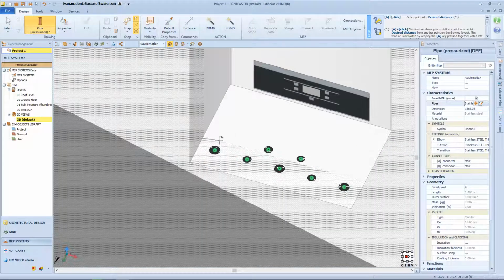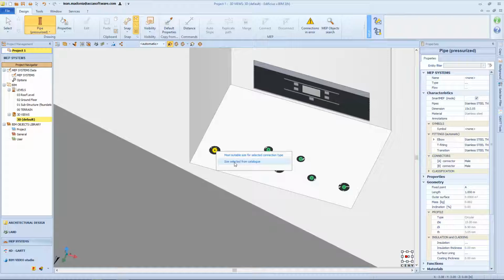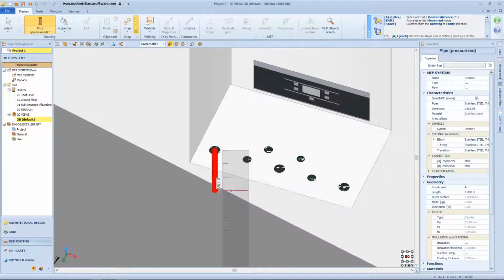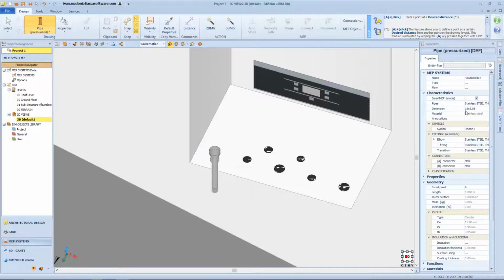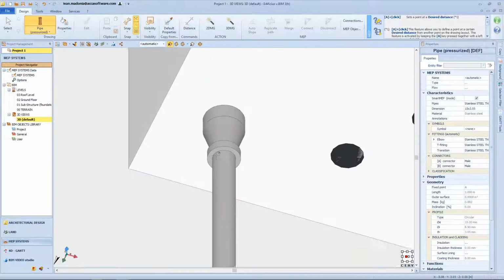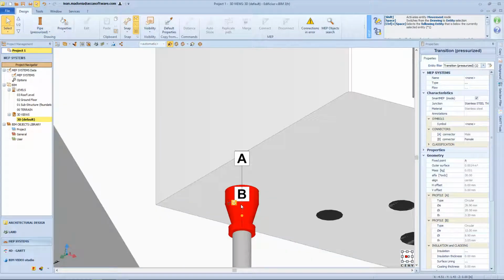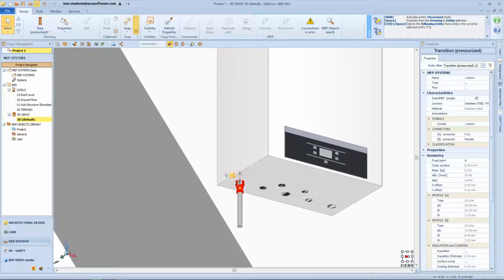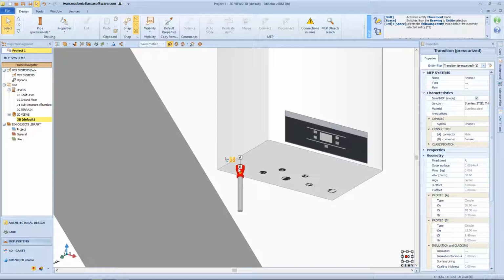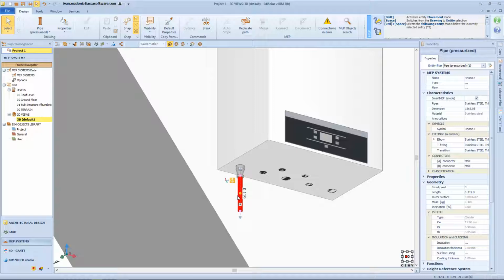By choosing to proceed with the dimension selected from the library, the connection entity chosen from the drawing menu will be arranged and subsequently configured. In this case, if the dimension assigned to the connection profile is not the same as the connector, any necessary transitions or fittings are automatically inserted. The direction and verse of the pipeline, in this case, are determined by the orientation of the connector from which the connection is being made, therefore the tools to support the pipeline tracing are not available.